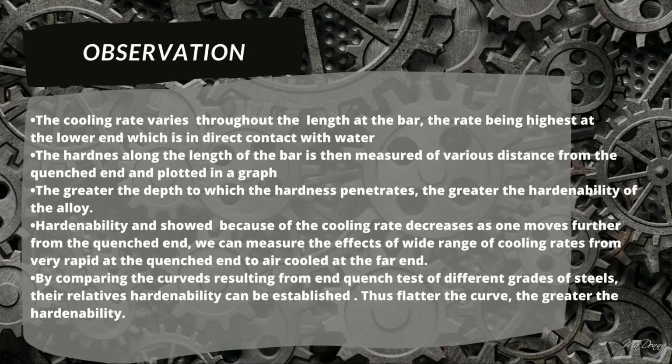the observation that we saw is, first, the cooling rate varies throughout the length of the bar, the rate being the highest at the lower end, which is in direct contact with water. Second, the hardness along the length of the bar is then measured at various distances from the quench end and plotted in a graph. Thirdly, the greater the depth to which the hardness penetrates, the greater the hardenability of the alloy.